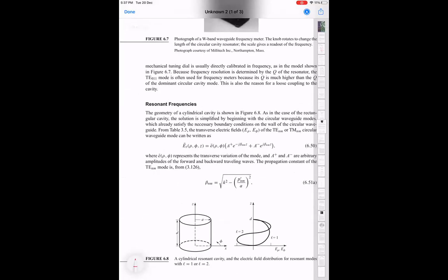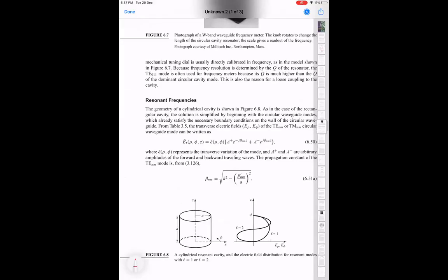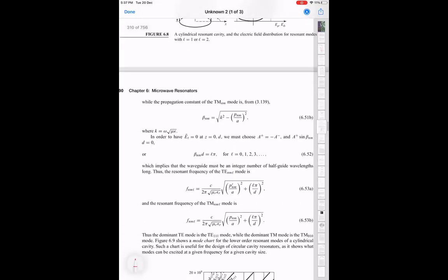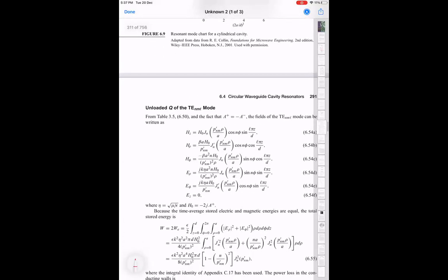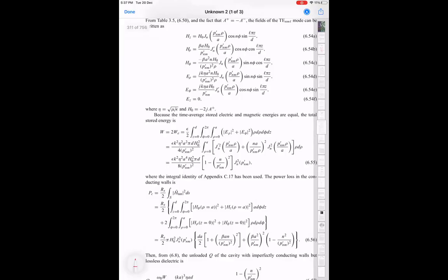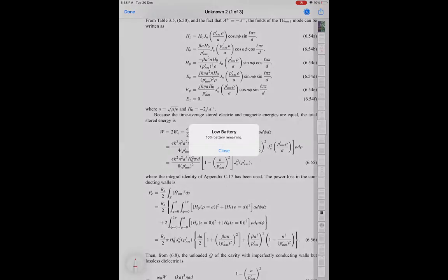Even a perfect sphere can be a resonator. The modes are going to have different shape. You can also just have a slab of dielectric. So here we said it's vacuum, where the boundary condition is all because of the metal. But if you just have a solid piece of a dielectric, let's say a high dielectric constant material, then the fact that at the edge of the dielectric you are moving from high dielectric constant to air is also a boundary condition.